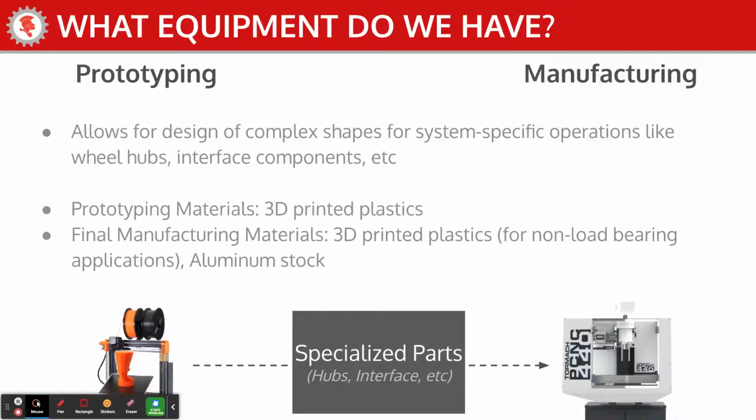When things are a little bit more complicated and not just simple flat parts or structural single cutoffs, I want to make sure you guys are designing it in a way that one is, yes, it's possible to 3D print, but two is also possible to make on actual legitimate manufacturing equipment like a mill, right? Most companies, and 3D printers just aren't here yet, most companies are not gonna give you a product that they want you to make that can't be made on a mill. So if you design it only for 3D printing and it's not feasible to make on a mill, you guys might not understand the difference there yet, but I can help you understand that if you want. Then they're gonna reject your part every single day of the week.